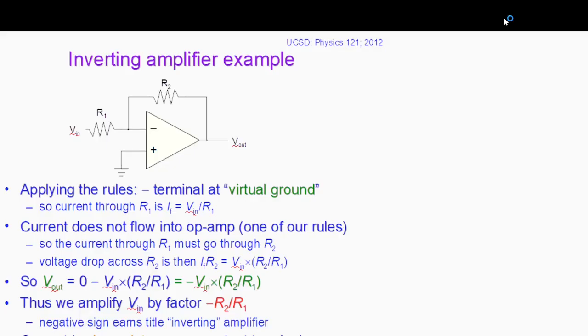Again, an inverting amplifier example. I think I already discussed it, but since these slides I found it very good, everyone has its own way to describe the concept. So these are, I'll say, a very good read for students to go through. But we have already analyzed it in the beginning, how this equation we derive for the inverting case: V out is equal to minus V in times R2 over R1.